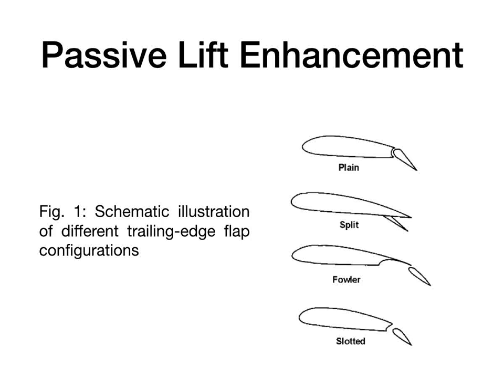Further refinements of the Fowler flap design involve using two or three flap segments. This design can lead to extremely high lift coefficients of up to around 3, but is complex and requires extra volume inside the wing to be stored during cruise. Single slotted flaps are most common on mid-size aircraft. Most larger commercial and transport aircraft use multiple slotted flap arrangements.